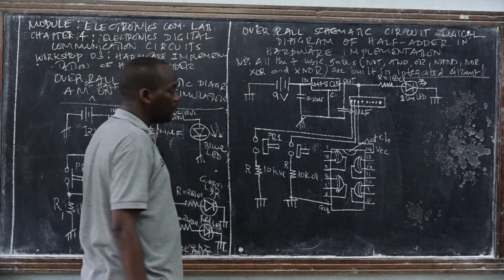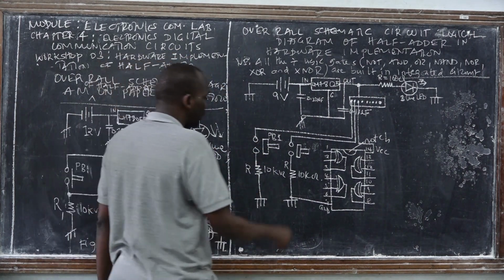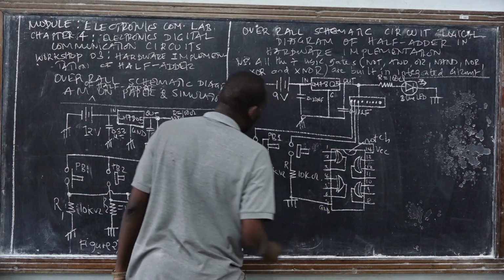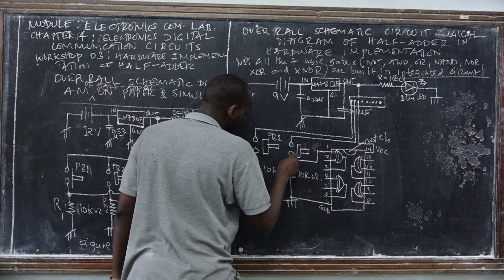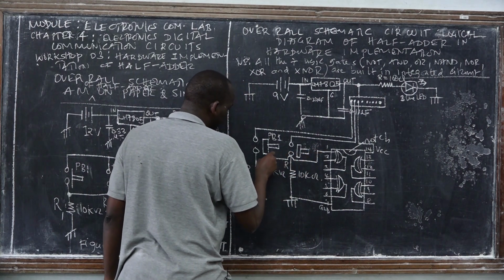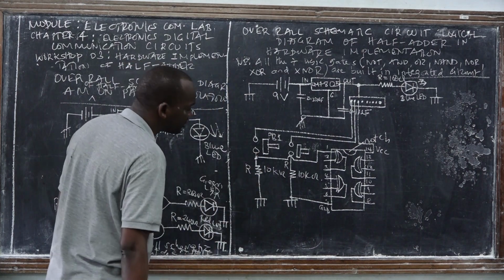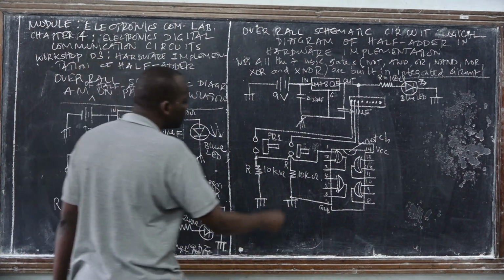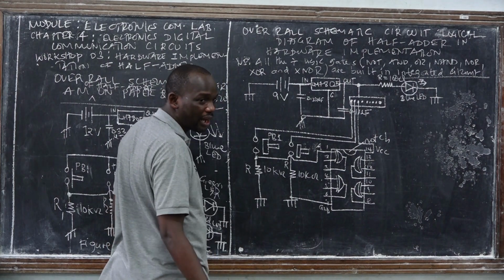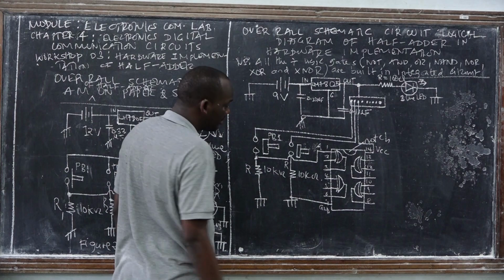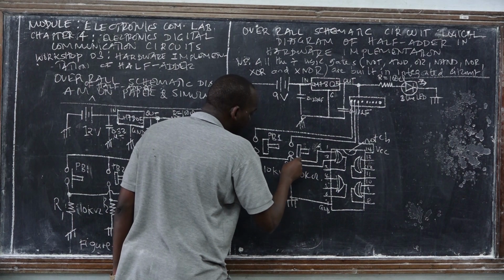So let us implement the exclusive OR gate part. It's simple once you have this diagram in hardware implementation. So pin number 1 is connected to the pull down resistor network number 1. This is what you used to call input A on paper and on simulation. Right?